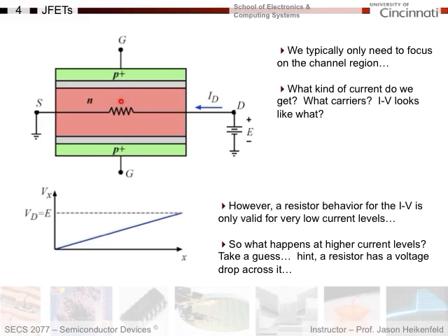This is just resistive semiconductor, right? And so if I look at my current versus voltage, it would look like a linear response of I equals V over R, right? Furthermore, because this is a uniform resistor across here, this is my positive drain voltage applied here. You can see that as I move in positive distance x across here, my voltage increases in this direction.